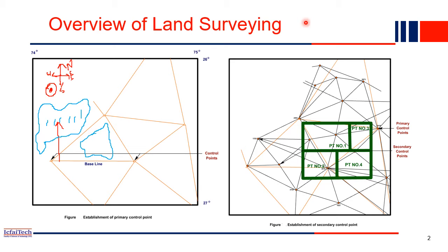Now these big triangles will be there, right? Already we found these big triangles. Now these big triangles can be further divided or classified again into small points. What we did at the beginning is we knew the latitude and longitude of only the control points. Now after this initial surveying, we know the latitude and longitude of this point, and like that, of all these triangular points.